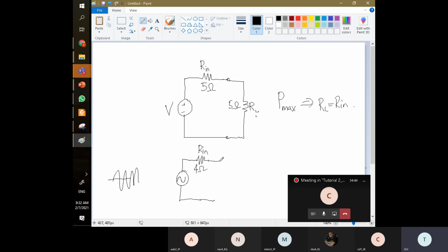After the output here, you will need to connect to your external speaker to hear the amplified music, right? When you're choosing the speaker, you can choose 4 ohm, 8 ohm, 60 ohm, or 32 ohm. Usually headphones use 32 ohm, and a really large speaker uses 4 ohm or 8 ohm.